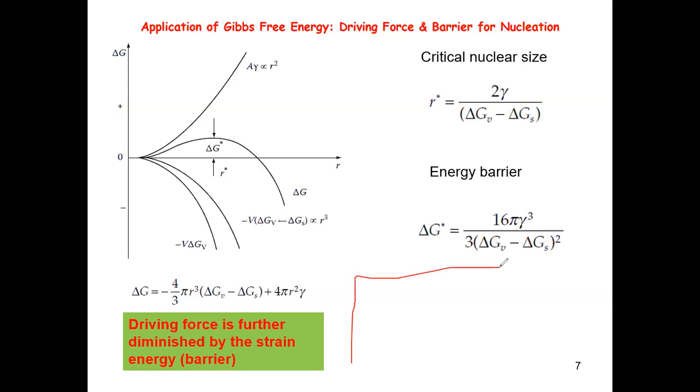In the solid-liquid transformation, it's very reasonable to assume that you have a homogeneous, spherical nucleus. But in the case of solid transformation, in most cases you will see a very non-spherical nucleus, a polyhedral nucleus, compatible with the symmetry, surface energy, and original crystal structure of your alpha phase. So that is also one thing which is quite different from this one.